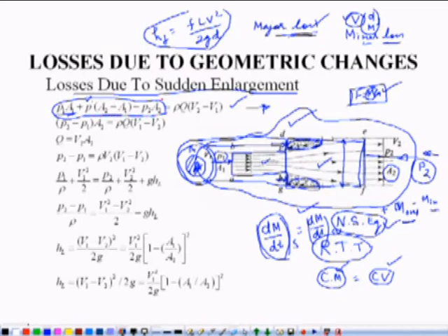So, this one on the left hand side of this equation is the force acting in x direction. Now, force acting in x direction, as per our momentum equation, is equal to rate of change of momentum in that direction for this control volume, right. For the control volume we have this equation as per the Reynolds transport theorem. Since flow is a steady flow, this term dm over dt becomes 0. So rate of change of momentum for control volume is 0 plus momentum going outside the control volume. What is momentum going outside the control volume? Since flow is steady, it is rho q multiplied by velocity.